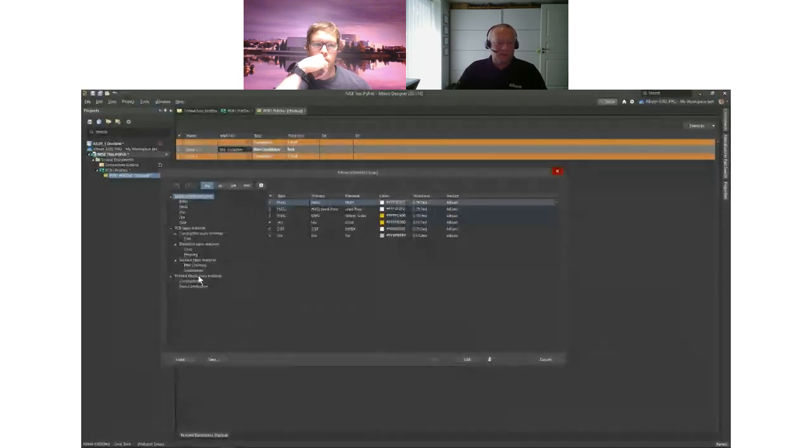Now let's have a look at the material library for it. So you can see here I have the printed electronic materials here. Now they are basically just 2 materials. I have conductive and non-conductive. So in here you can see for the conductive side I have added the TactoTek silver ink, 2 mils. You can of course add your own. Just click new here.